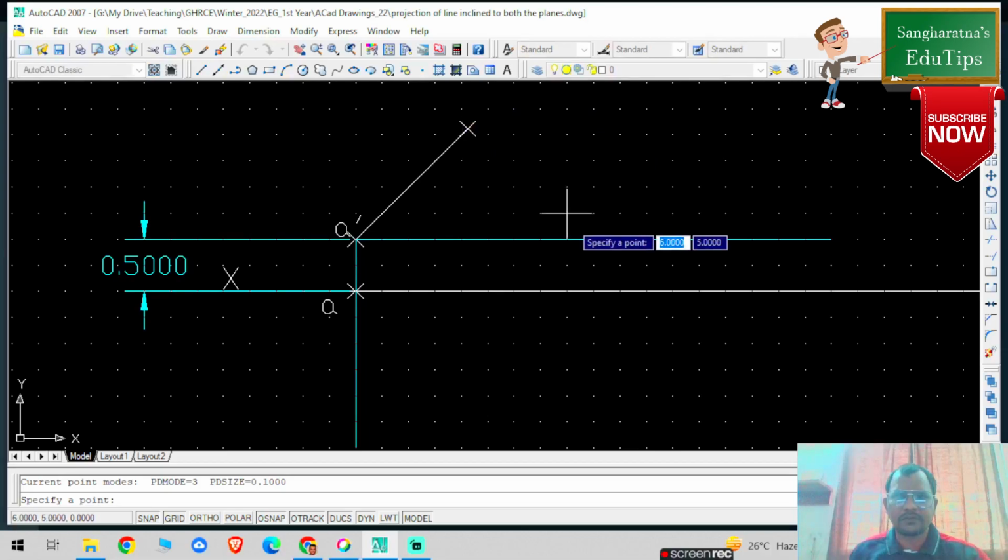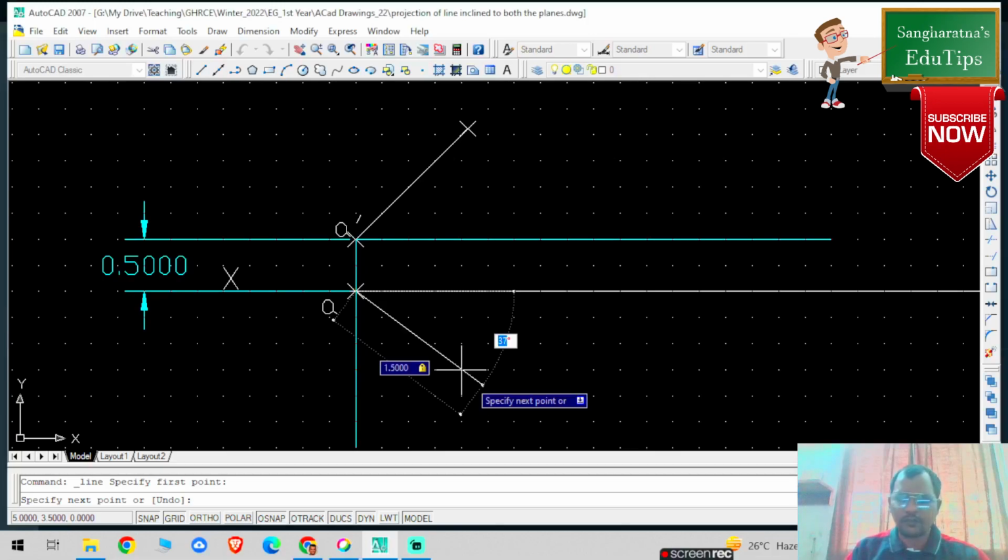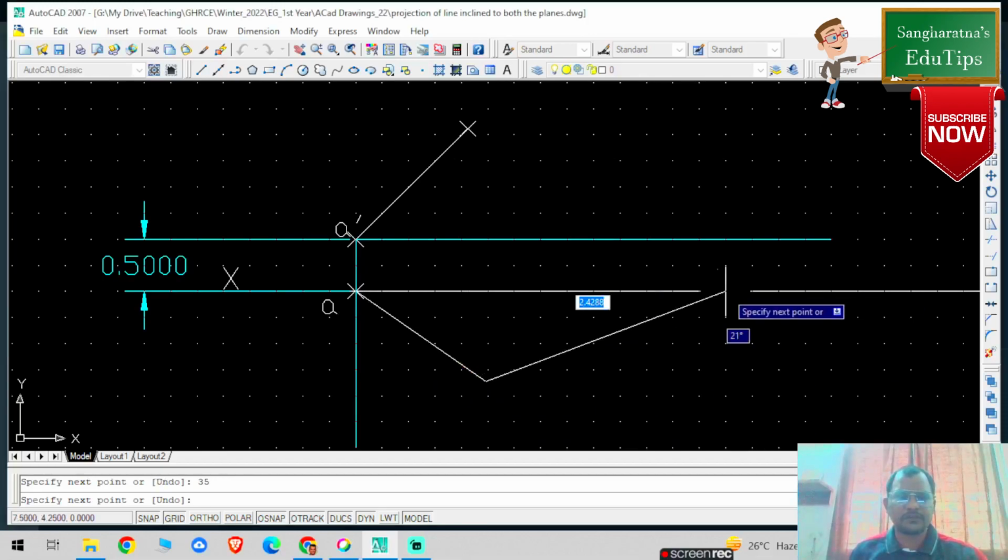Similarly, from this particular point I need to draw another line, which is 1.5 AutoCAD units and 35 degrees inclination with VP. Its inclination with VP can be seen in the top view, that is on the horizontal plane. Then press enter, then escape.